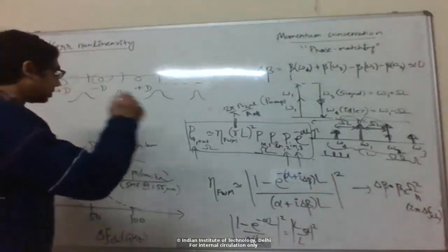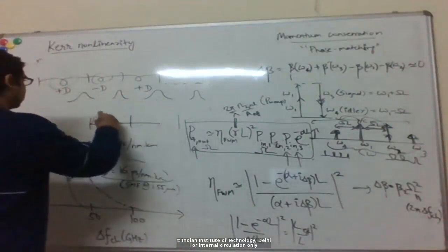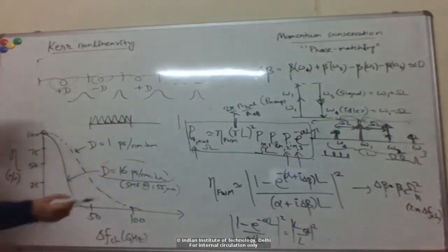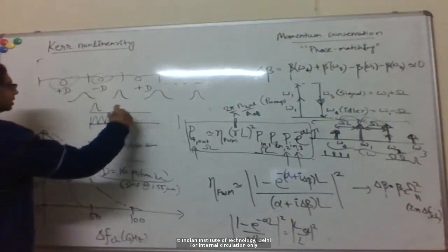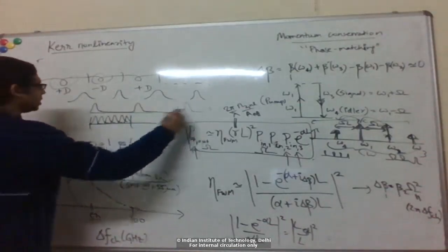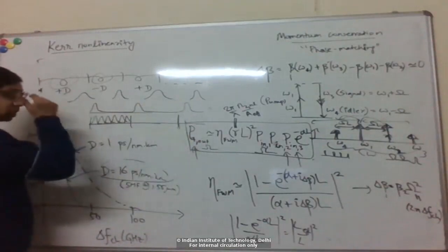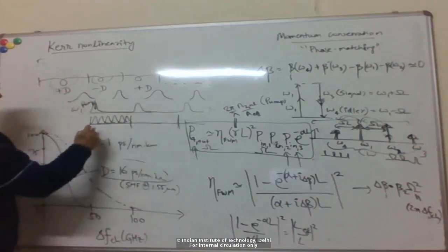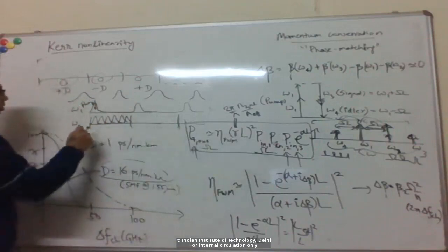And you can also do this demultiplexing of TDM signals that we talked about with cross-phase modulation. You can do the same thing with four-wave mixing. Let's say you have a pump pulse frame which has a repetition rate at the signal you want to demultiplex. This is the pump, or omega-1 here, and you line up with your signal, or omega-2 here.